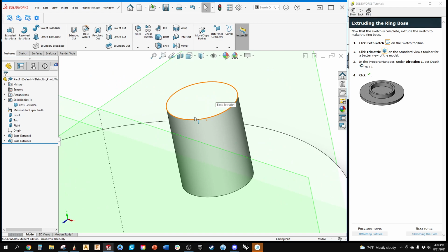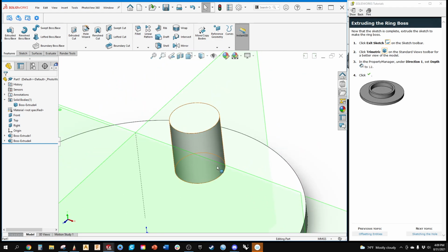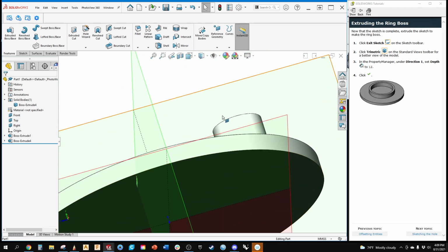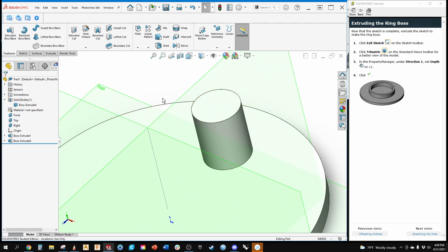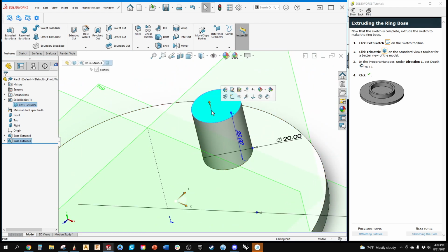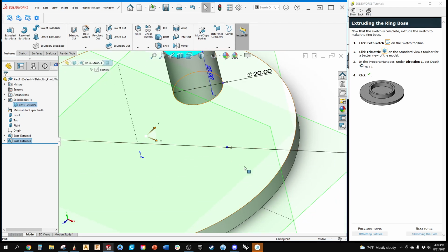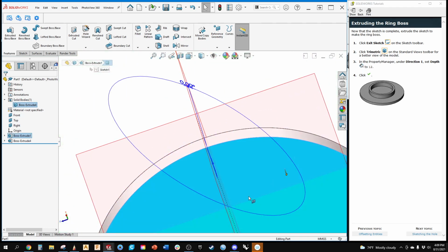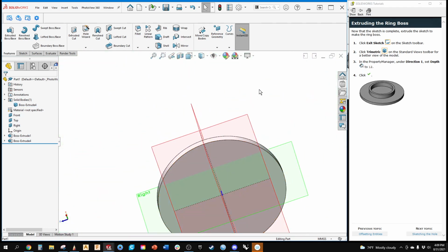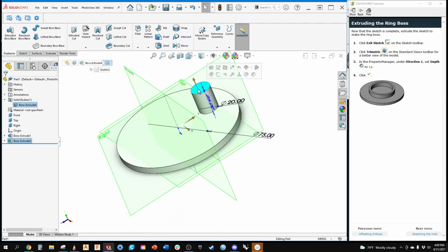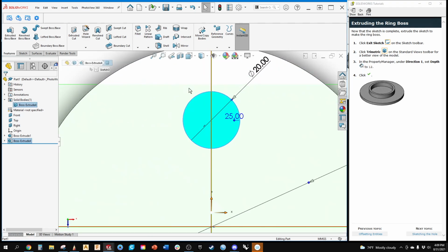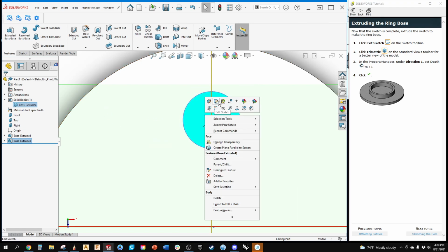So I need to put a hole that goes all the way through here. So again, I'm going to do a sketch, and I could do a sketch on this surface, or on this surface. It makes it easier if I do this, because when I go to plane, I have that item. Now, right click, I'm going to create a sketch.